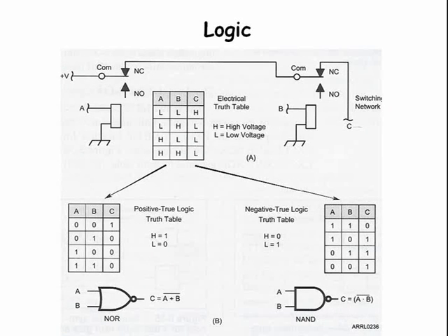It is common for many ICs to be connected in parallel on a data bus or address bus to share data or addressing information. In this configuration, only one IC output can control the signals of the bus at a time. All other IC outputs must stand by, by changing their outputs to a high impedance state without attempting to drive the bus to a high or low state. ICs with this ability are called tri-state logic, where their outputs can be high, low, or high impedance.